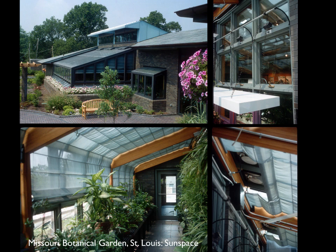Here is a sun space, which is a combination of a greenhouse for growing plants and starting seeds and so forth at the Missouri Botanical Garden in St. Louis. It's also a sun space, and the building is a passive solar heated building. You can see the exterior of the sun space on the upper left. So it has a roof, a south wall, and an east-facing wall that are glazed. The east-facing wall, remember, is not really providing much winter solar gain, but in this case it would be providing extra light to the plants.